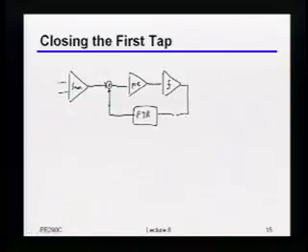For that very first tap, things tend to be a bit nasty for the following reason. We've already said that this DFE summer here is self-loaded because of the taps. In other words, there's this intrinsic speed limit, or really, if I get close to that speed limit, it starts costing me a lot of power to actually do it.